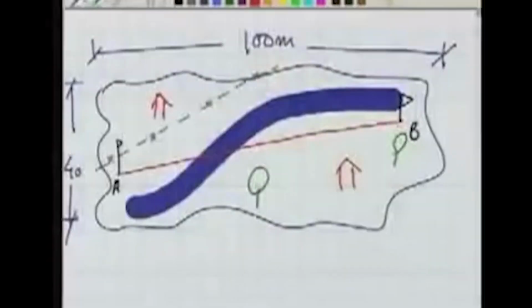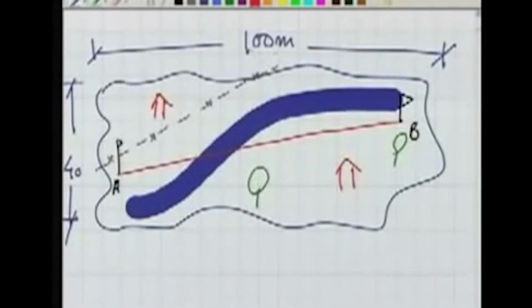Once we have located these 2 points, job number 2 in working from whole to part is we want to measure the distance between point A and point B using chain or tape. We already know how to measure the distance. As you can see over here, this distance AB is of order of 100 meter.